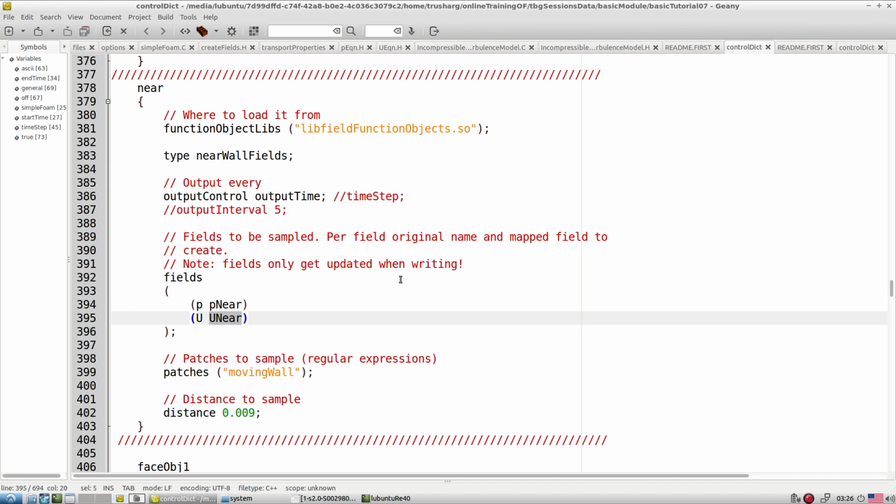This is sometimes useful to calculate the wall bounded streamlines, sometimes called limiting streamlines, exactly how the streamlines look on any wall. Normally we know that on the wall the u, v, w components are all 0. So if you try to draw a streamline, it is never going to happen because all components are 0.